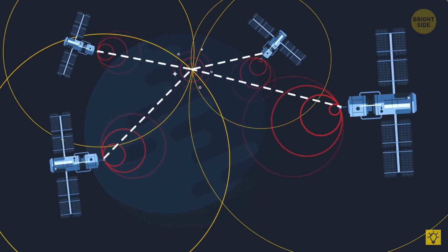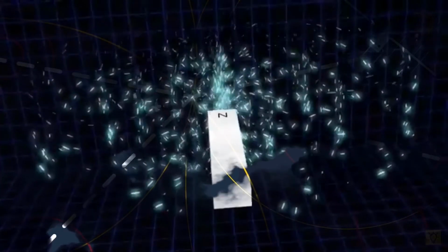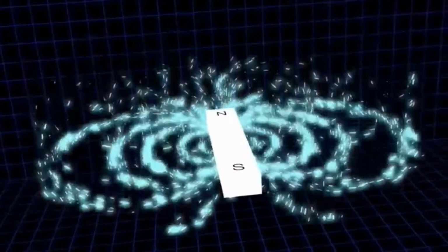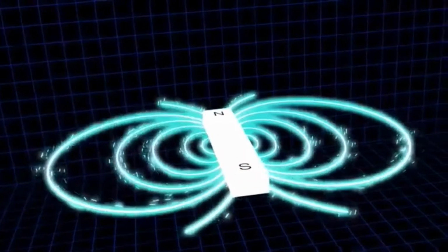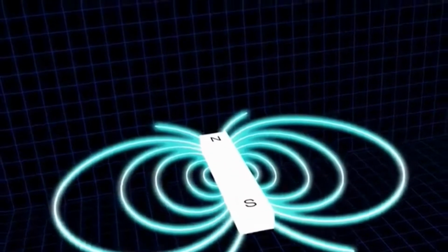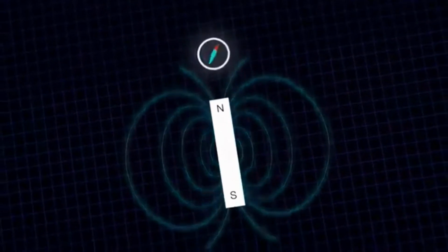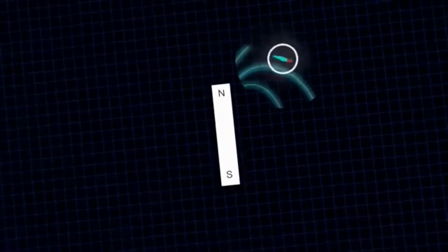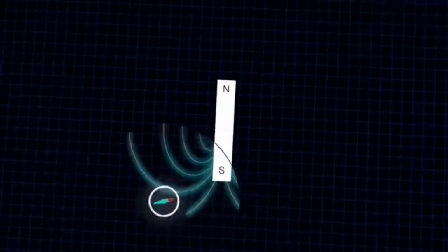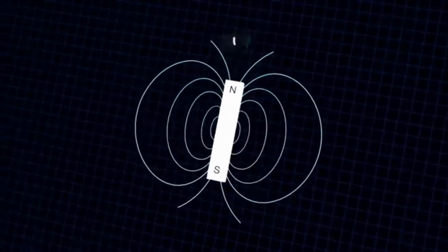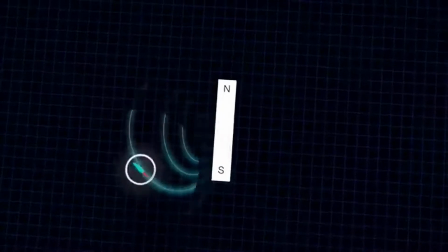range. In order for the drone to fly autonomously, the drone should identify a heading using a magnetometer. As its name implies, a magnetometer measures the strength and direction of a magnetic field. Using this principle, a drone can always determine the direction of the magnetic North Pole and adjust its trajectory accordingly.